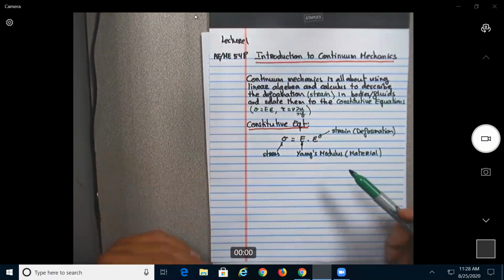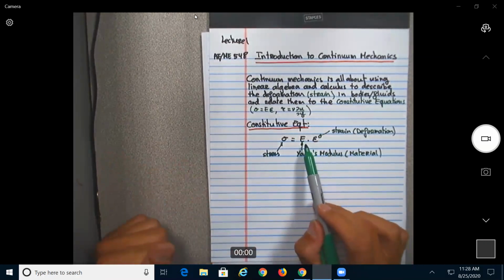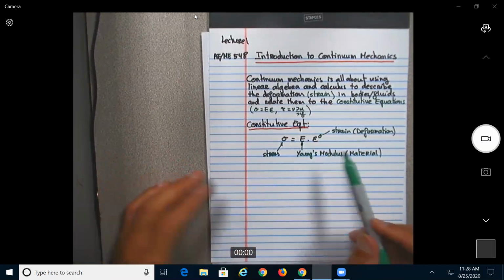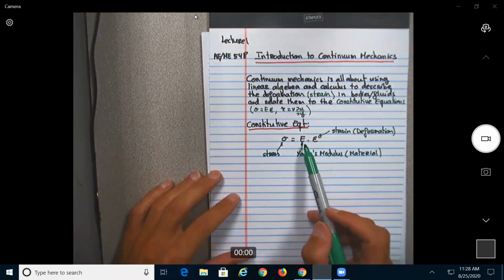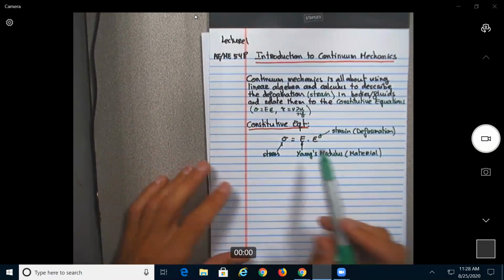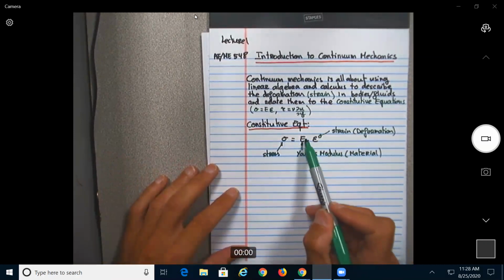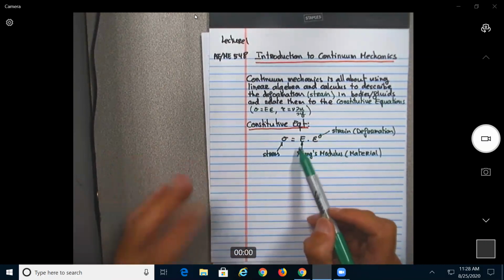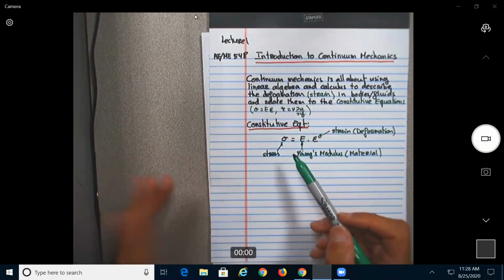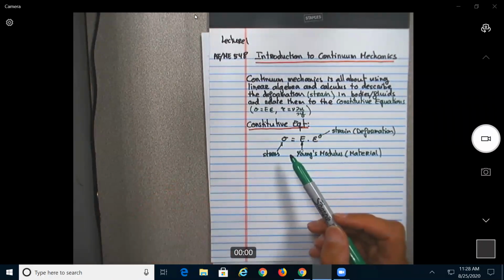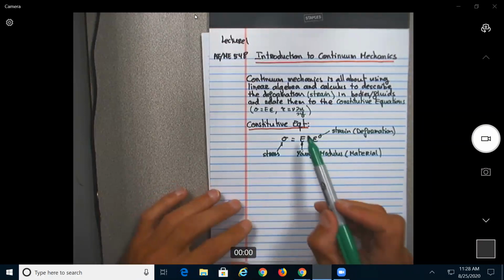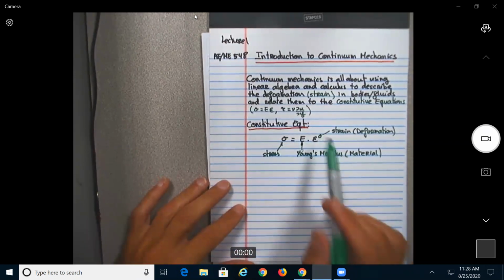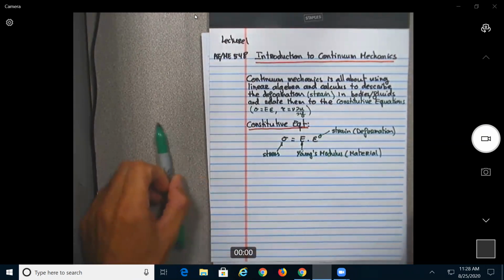So obviously here, this is a simple case for an isotropic material, but you might have materials like composites, no, that can be orthotropic and so on. So all this equation here takes another shape, no? This is only one component, but if you have orthotropic, you have 3 components. I think this one will be a matrix of 9 different components, okay? If you have 2 axes of symmetry, I think it's 18, and then you can have up to 81 if you go to the completely without any axis of symmetry. All right. So this will be for solids, okay, for solid bodies.